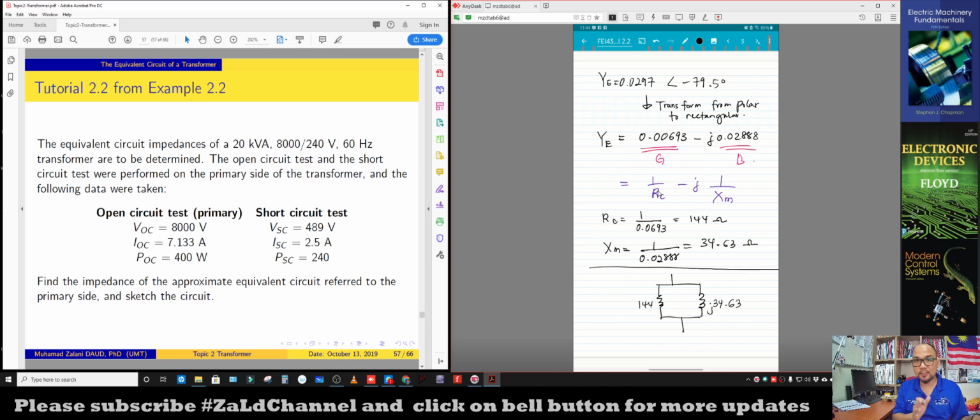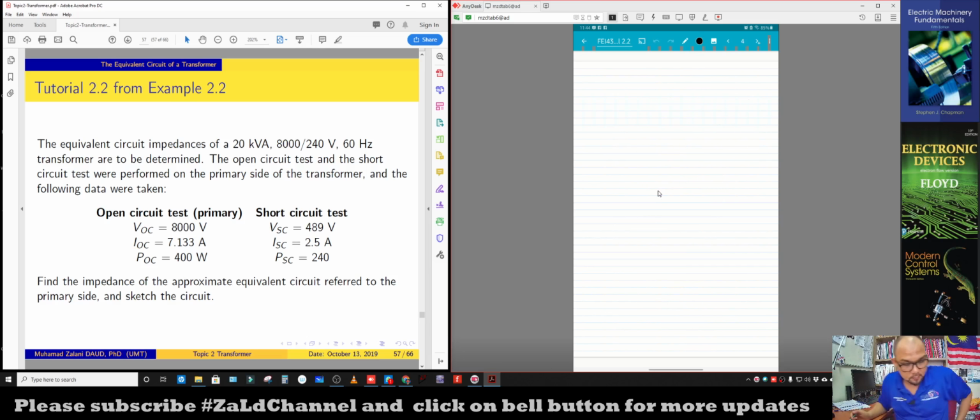Now, from the short circuit test, we are going to determine the other values, which are the series components. Firstly, we have the values of the short circuit test here. First things first, we are going to find the power factor during the short circuit test.